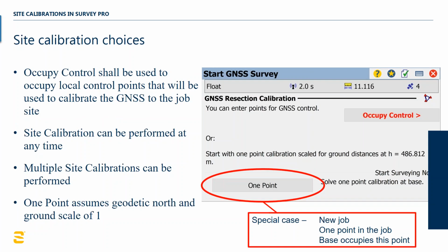And maybe just to chime in here on that topic, Joe, the equivalent setup that you get here is, imagine if you put a total station on the ground, plunked a nail in the ground, gave it whatever coordinate you like to begin, say 5,000, 5,100, and then you did an old-fashioned sunshot establishing a geodetic azimuth of that station. That's essentially what you get in this special scenario of a 1-point calibration.